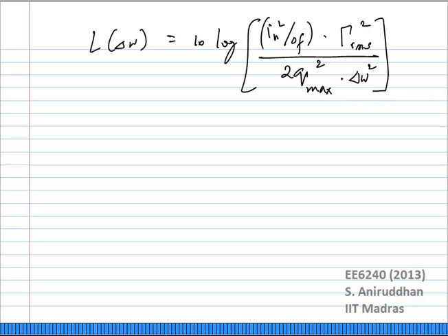Now, we quickly looked at flicker noise yesterday, so let's do that also. Fundamentally the way you adapt this particular model to take into account flicker noise is to write the 1 over f noise in terms of the broadband thermal noise and the 1 over f noise corner.